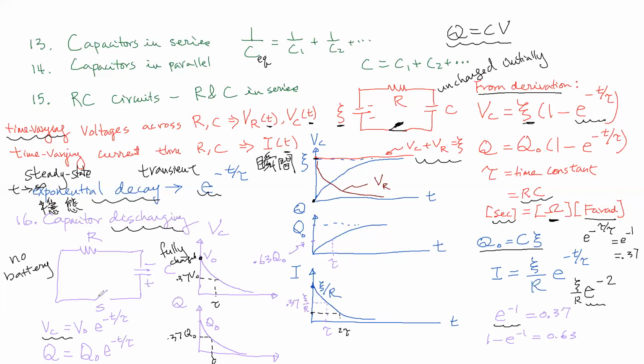Basically, you would start it, so you close the switch, and then the charge on the C negative plate, the electrons will start moving toward this side here and come to this side to neutralize it. So more and more, this capacitor will become less and less charged. It eventually becomes 0 when the time approaches infinity.